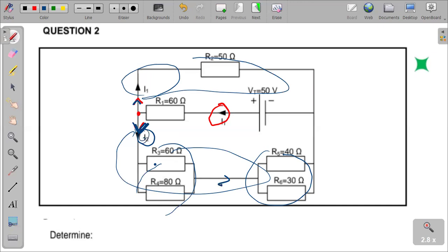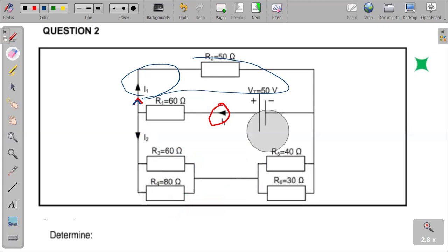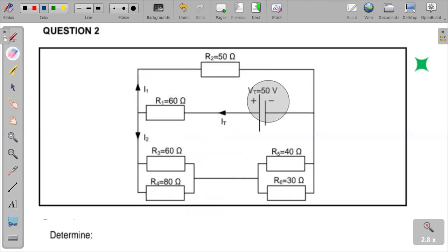So we can also safely say, as long as resistors are experiencing the same current, or the same current flows through the given resistors, those resistors are in series. And as long as current is divided among resistors, those resistors are in parallel. So how many parallel combinations do we have? Let's try to figure them out together before we answer the questions.